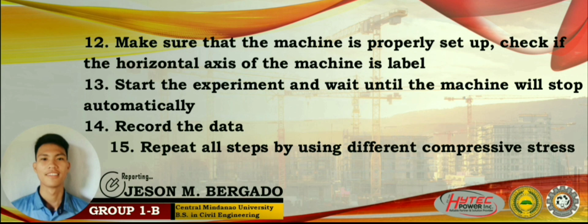Check if the horizontal axis of the machine is leveled. So may bubble na nakalagay dun. Start the experiment and wait until the machine stops automatically. Then record the data. Then just repeat all steps by using a different compressive stress.